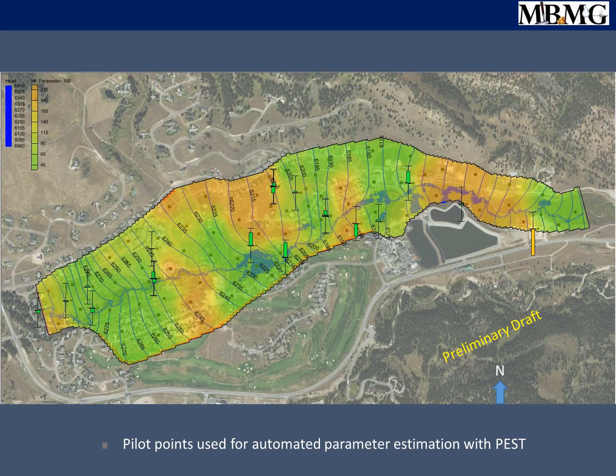So now you can see the difference between the orange and the green. The orange is where the contours are a little more widely spaced, and the green is where they're more closely spaced. And that's just this optimization program. It makes adjustments to hydraulic conductivity until it matches and gets the calibration targets optimized. And as you can see, it's just a range, like 50 to 200 is the range I used. And in real life, hydraulic conductivity ranges over 13 orders of magnitude, an order of magnitude being multiples of 10. So it's actually a very narrow range compared to what it could be. So, any questions on that?